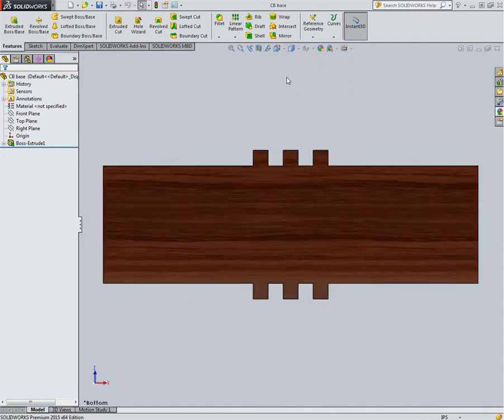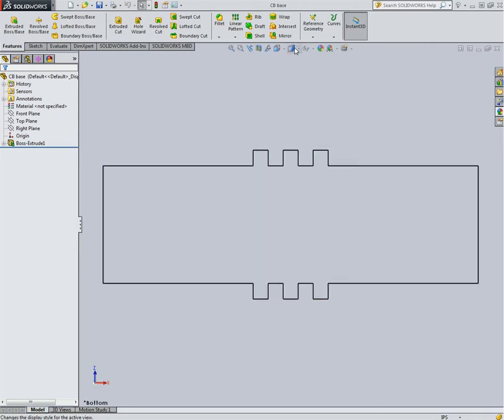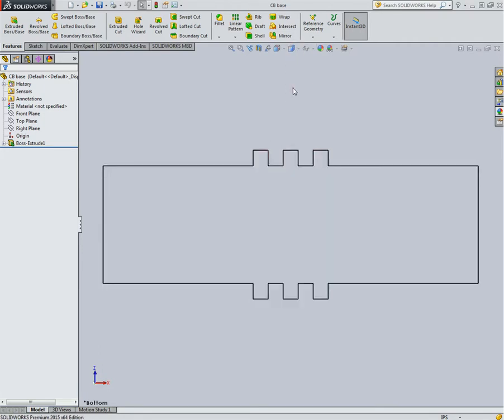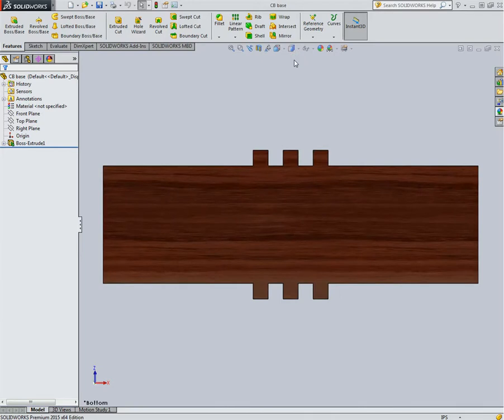And then the other cube will let you change the shading on the part, and you can use this to help you visualize your parts when there are more complex parts. Finally, with the glasses, there we can select or unselect different things to show, from axes to points to coordinate systems, etc.